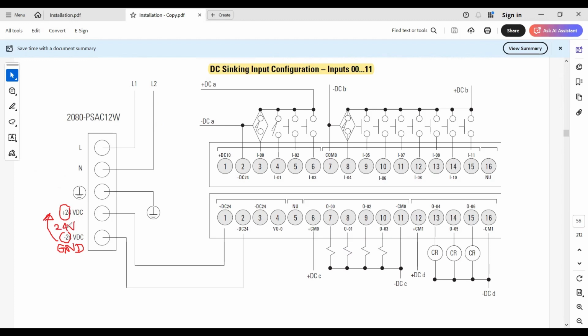These are some terms normally used in industry. Even though it is mentioned minus 24 volt, actually it is not minus 24 volt with reference to the ground, but you can consider this as your ground. Ground and earth are not the same potential, right? You should not short circuit minus 24 volt with your earth.